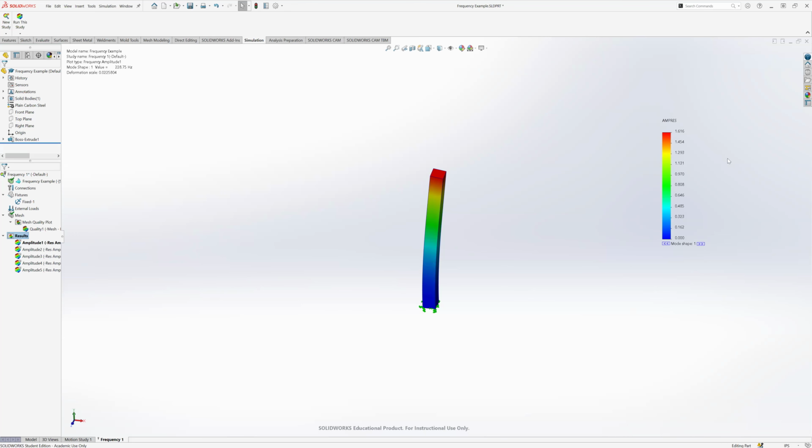So the main thing you would want to get out of a frequency analysis, if you want to stiffen something, is this: let's say you're doing physical testing, and you figure out the vibration this thing is going to be exposed to is maybe 200 hertz, and mode shape 1 is at 230 hertz, which is a little bit too close. Then you could make it thinner, bigger, whatever, to stiffen it or not, and that would adjust this frequency either up or down depending on what you do.